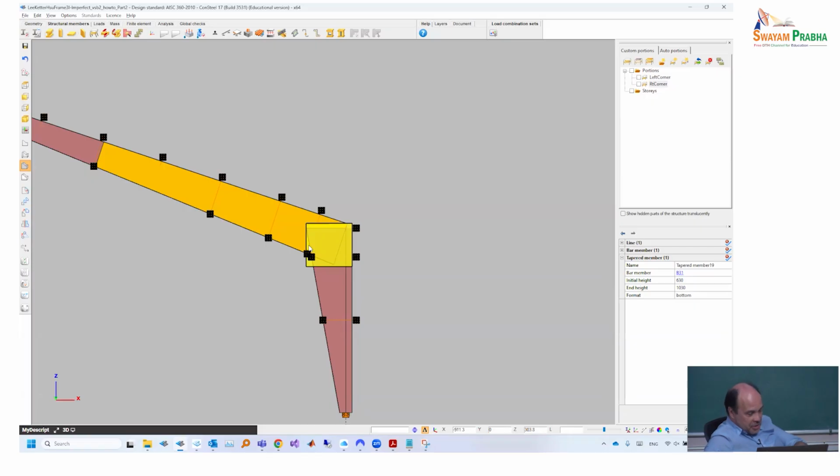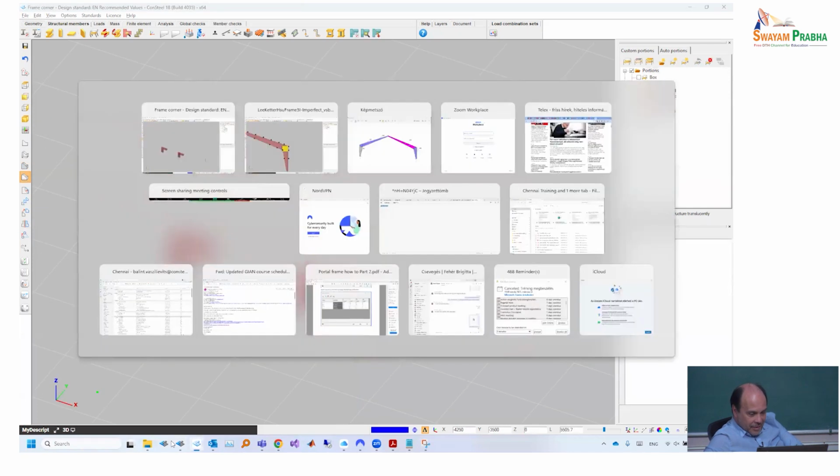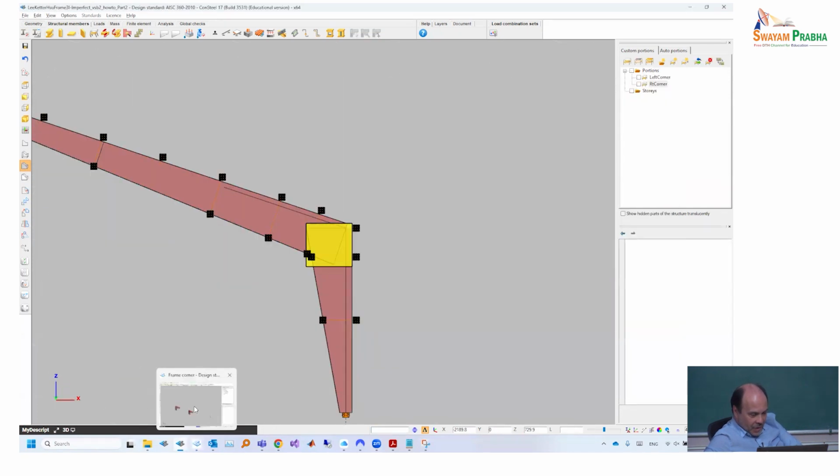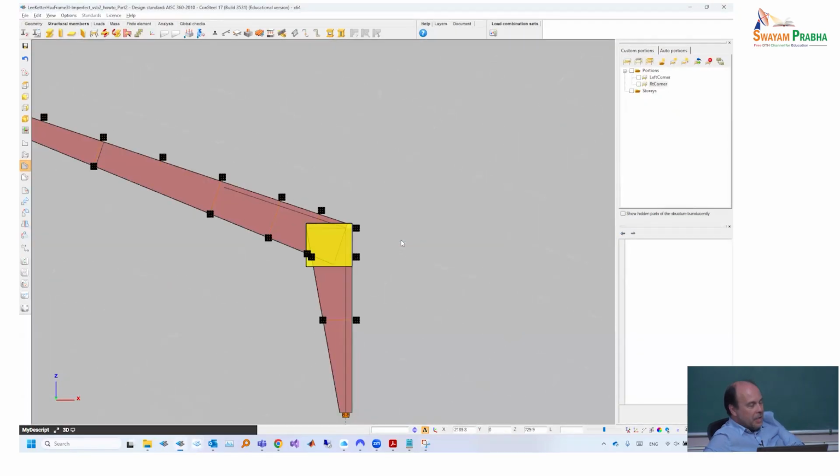So because of this, in the original model, where Professor White said that he expects overstress in the rafter only, he artificially increased the beam depth in a way that they will exactly reach the reduced expected size at the boundary of the column. So that's why it's another geometry calculation, but you can figure out what depth you need where the column and the beam intersect to get 1,000 depth. This is normally, for a normal engineer, they don't care. Right. But we're not normal.